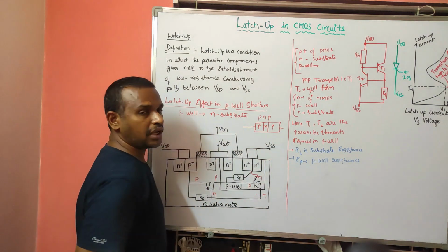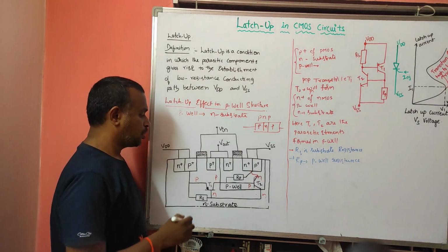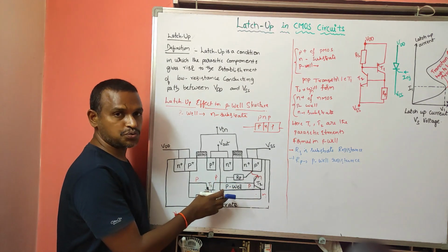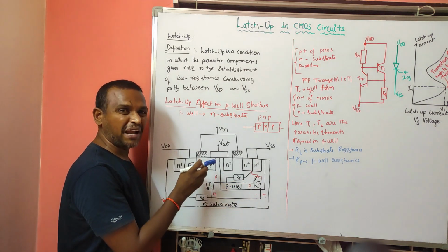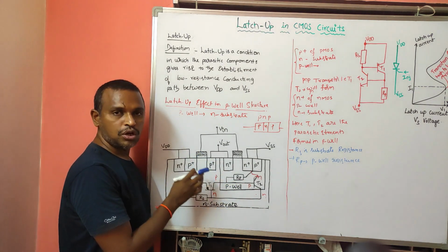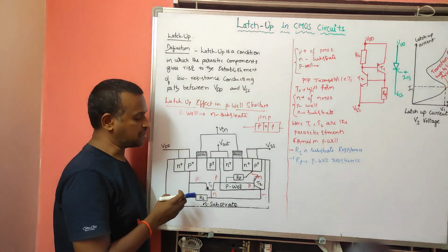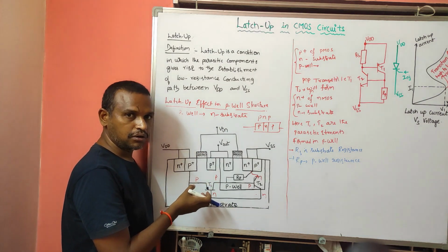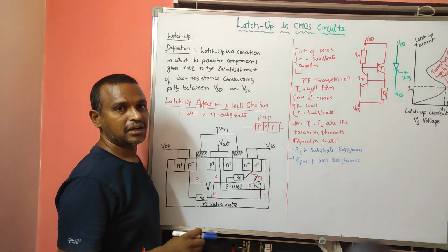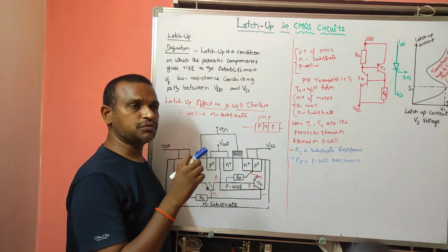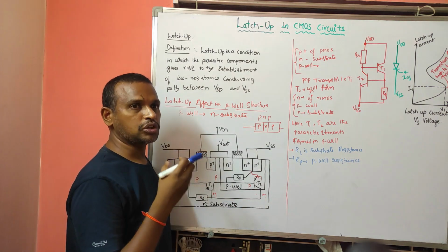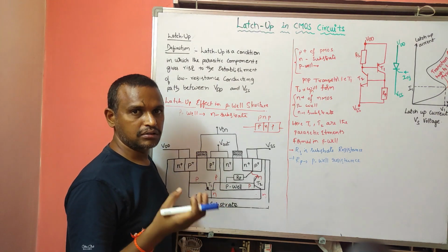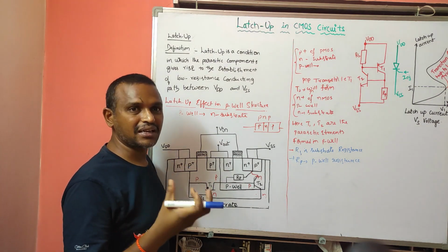Combinedly, two transistors are formed, T1 and T2. These two are called parasitic transistors. What do parasitic transistors mean? Because of the fabrication process, we place our required NMOS and PMOS. Because of those materials, there will be a formation of extra devices, that is, parasitic elements.